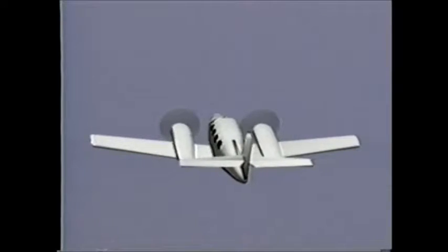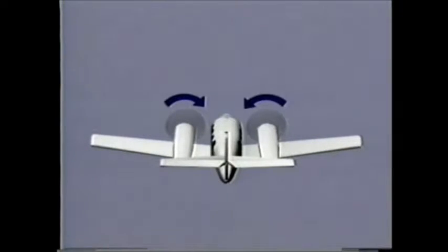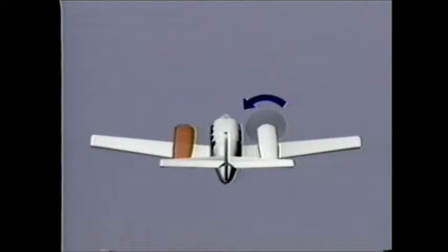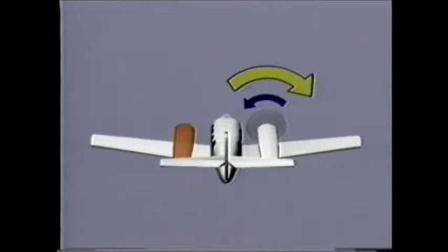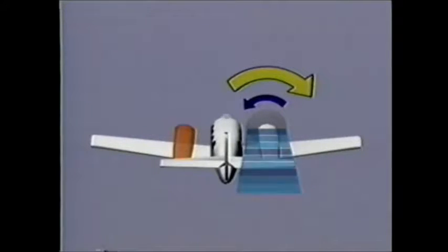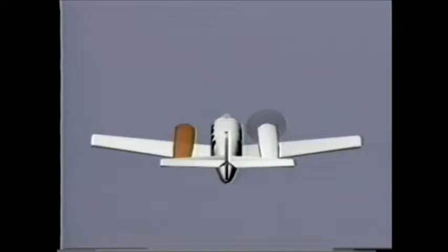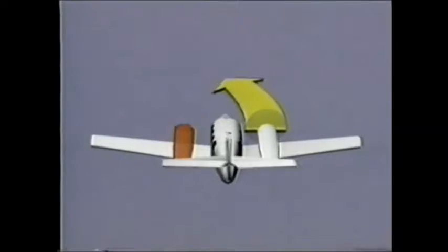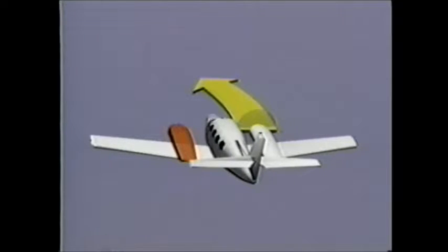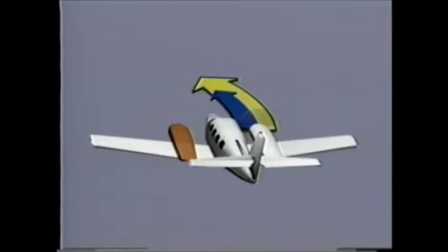Although these same factors are present in aircraft with counter-rotating propellers, the prop rotation minimizes some of the adverse effects. For example, if the left engine fails, the torque of the operating propeller now opposes the asymmetrical lift generated by induced airflow and reduces the rolling tendency. Asymmetrical thrust still causes a yaw toward the failed engine, but the effect of P factor is less. This is because the descending propeller blade is always the one closest to the longitudinal axis.